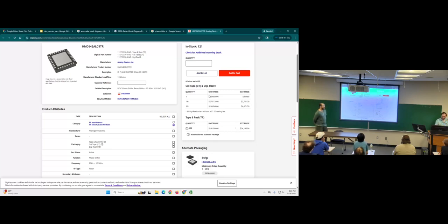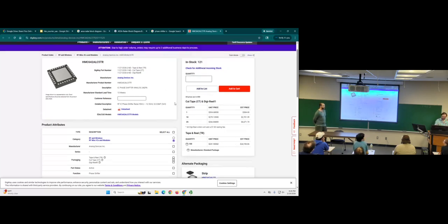So most of the radar technique frequency range is in the gigahertz. Yes. Does radar operate at super low frequency? Absolutely. But there's the physics of wavelengths for resonant elements. Let's say you're making an antenna, generally an antenna should be about half a wavelength. You can go higher, but it's not necessary. We like our antennas small if we can. Standard rule is half a wavelength.